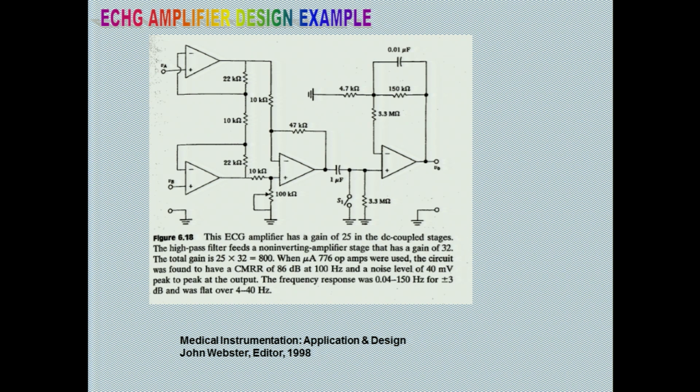Similarly, you want like say 65,000, so you have 800, you have to multiply that. So we will have 3 stages for EEG, remember that. Under no case can we have only a single stage. Minimum 2 stages for ECG and EMG. For EEG you must have 3 stages. If you put 2 stages you get no partial credit also, because I am telling you now, 0, easy for me to grade.